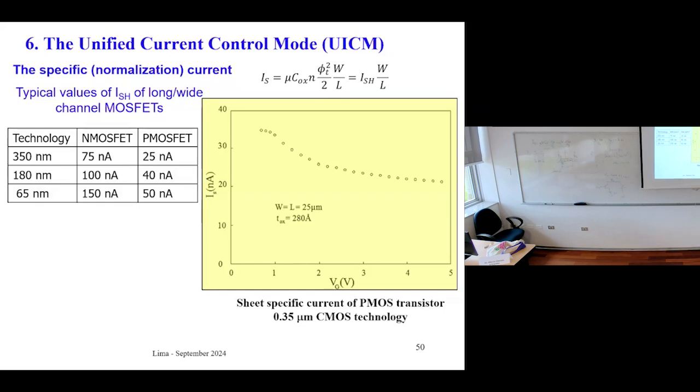5 or 6 is 20% of 30. I would say it's an average value of 30 plus minus 20%. You say this seems to be too much. It depends. Sometimes you operate your device in a very small region of gate values. This is an old technology because it accepts a gate voltage of 5 volts. Typical technologies of today accept 1.5, maximum 1.2 volts at the gate. So the variation of the gate voltage is much smaller than in this case here.